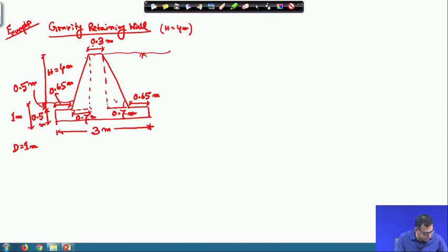So, the alpha value I can calculate. The properties are given, I is equal to 0, with no inclination. So, beta value, we can calculate the alpha value as tan inverse of 4 meter up to here, plus another 0.5, so 4.4 meter plus 0.5, divided by 0.7.